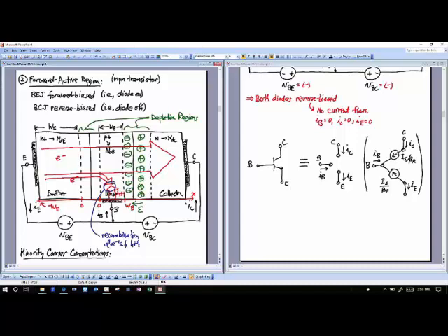Okay, you may say, hey, that's great, we get base current. No, that's not great. Because the base current is supposed to just be our control. And we don't want any voltages or currents to be on the base node. Well, we're going to put a voltage on the base node. We want to control that voltage. But we don't want current to flow into our base. Right? We'd rather have an MOS transistor where no current flows in. But unfortunately, current does flow in. That is the source of your IB in your op amps. Right? That input base current, this is it. Right here. You want that as small as possible. So you don't want this recombination to be happening, but it happens. Okay, you just have to live with it.